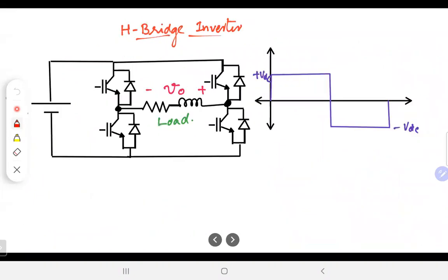Now, if it is a full bridge inverter, what we call the H bridge inverter, then we have 2 legs. Okay, so this is leg A and this is leg B. I think I have named it the other way around. Let me name this as leg A. And because my voltage is defined as this one, this is point A, node B, and we have VAB, which is a floating voltage. There is no fixed reference, because point A as well as point B can be connected to plus VDC or minus VDC.